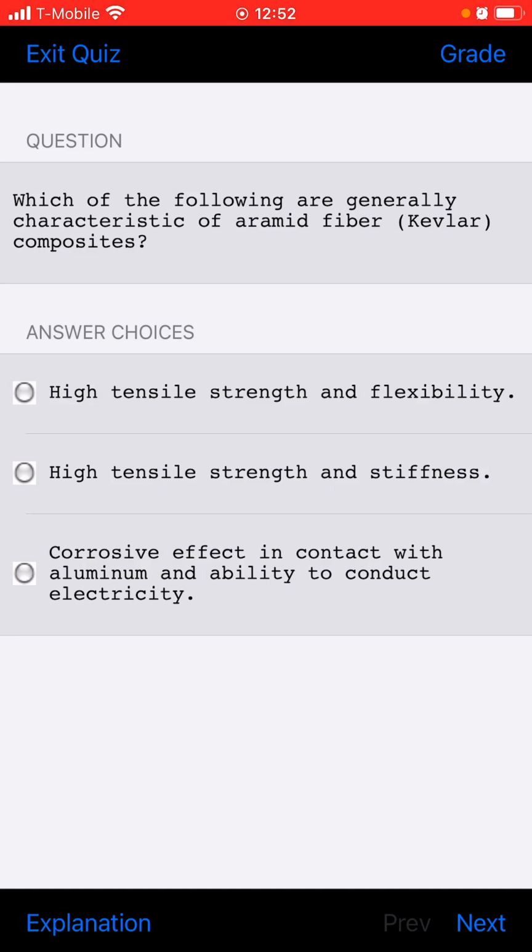When repairing puncture type damage to a metal face laminated honeycomb panel, the edges of the doubler should be tapered to 100 times the thickness of the metal.